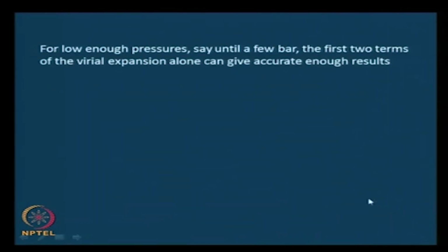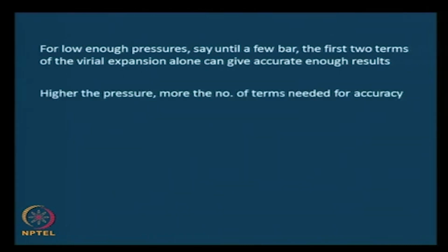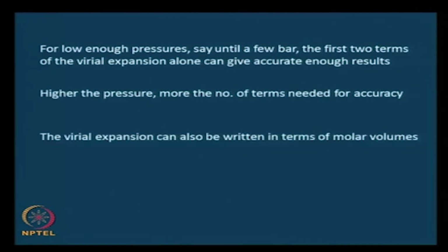Also, for low enough pressures, say about a few bar, just the first two or three terms of the virial expansion are good enough to give an acceptably accurate representation of the gas behavior. But the higher the pressure, the more terms are needed to accurately represent the behavior.